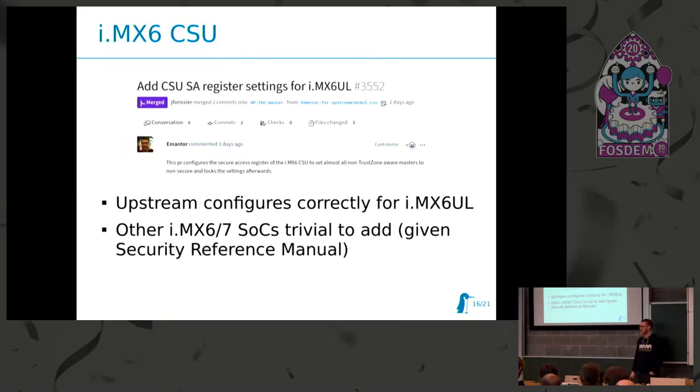So there are devices like PCILeech and this kind of devices if you have PCI on your i.MX. No, I unfortunately don't have open PCIe ports on the i.MX6UL. It's too small for that. But that would be a possibility on bigger platforms like i.MX6 Quad, which has a PCIe port.